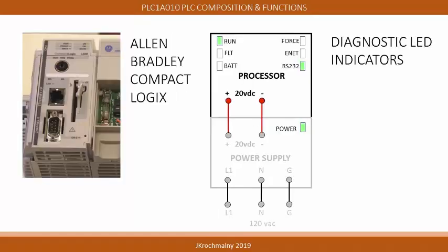The Allen Bradley CompactLogix processor is shown in the graphic. All PLC components will have diagnostic LEDs that provide information on their status. In the case of this processor, diagnostic LEDs indicate 6 conditions related to the processor.